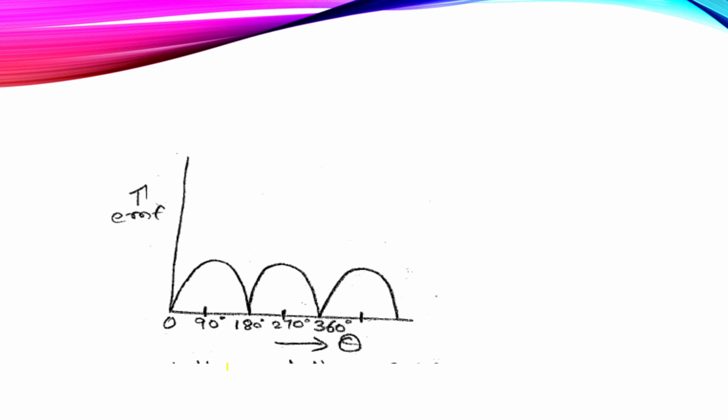In the first half revolution, current flows along ABLMCD, with brush A in contact with segment S1 and brush B in contact with segment S2. In the next half revolution, the direction of the induced current is reversed, and at the same time the positions of S1 and S2 are also reversed. So the current obtained is a unidirectional current.